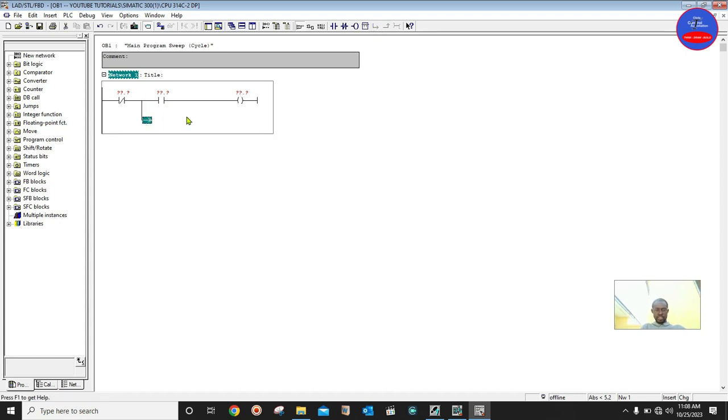The arrow is showing that we can insert a new contact. So we click on the open contact. Then we can select this line, and then you select close branch, with this contact showing the top arrow. Now we have closed the circuit like that. So now this is our simple DOL starter.